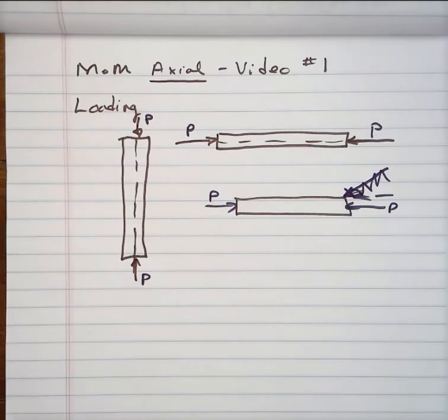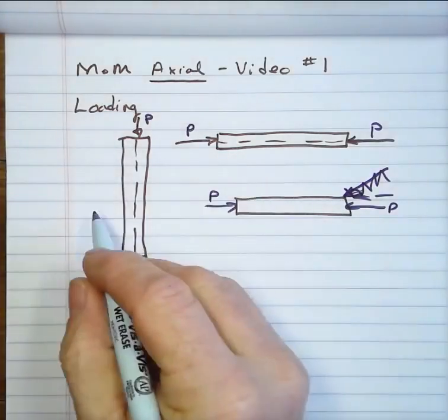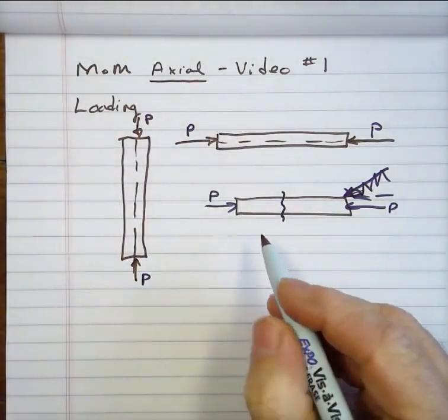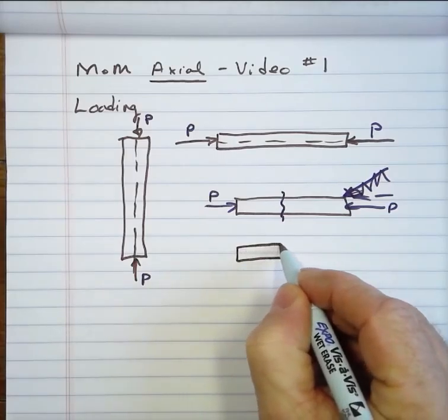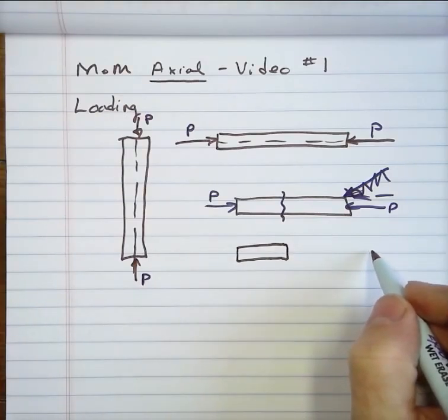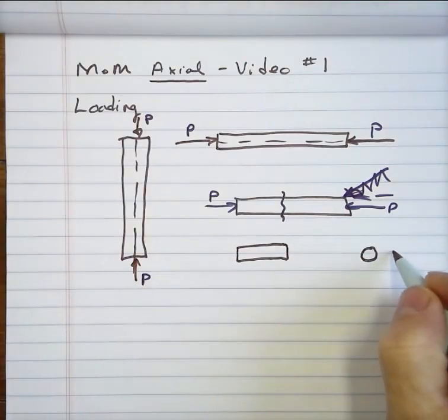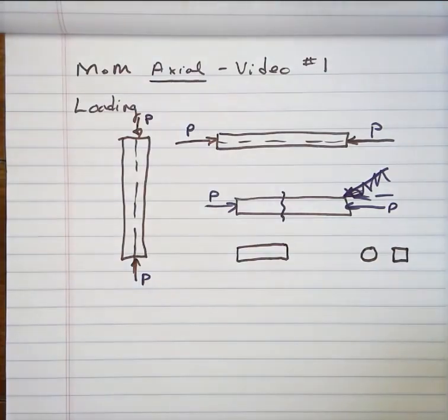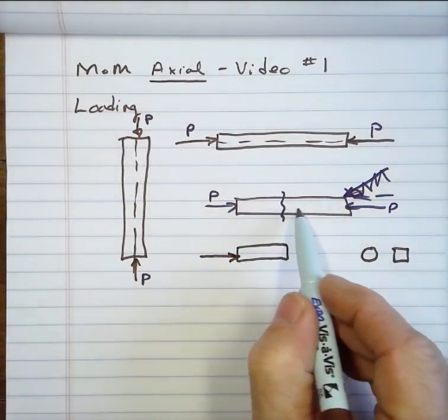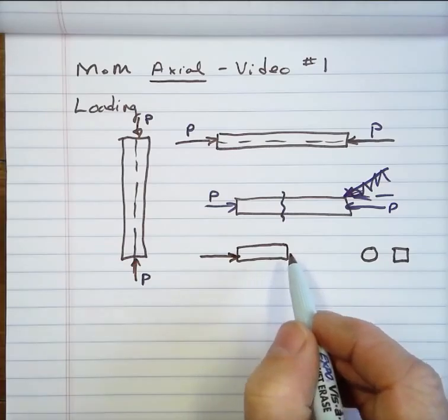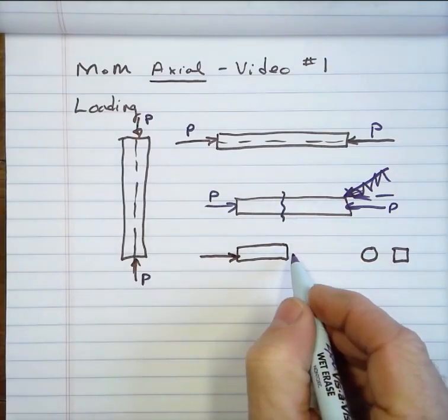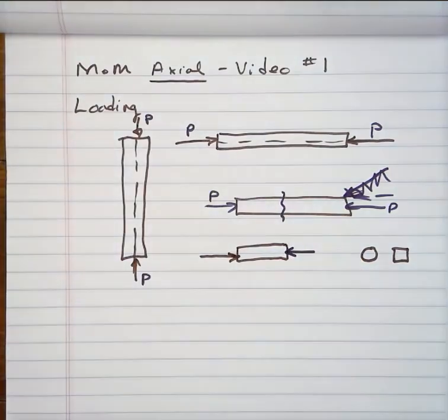And the stress, which acts, if we were to take any one of these, let's take this one right here, and take a look at its cross-sectional area. Maybe it's circular, maybe it's square, maybe it's rectangular. If this whole object is in equilibrium, that means every subpart of it is also in equilibrium. So if I draw a free body diagram here, I would get equilibrium.